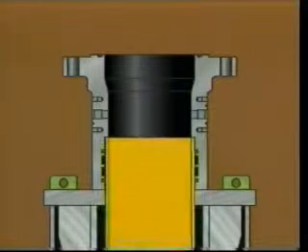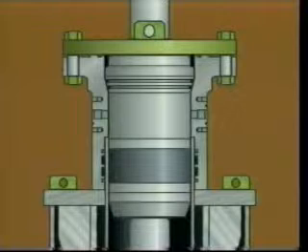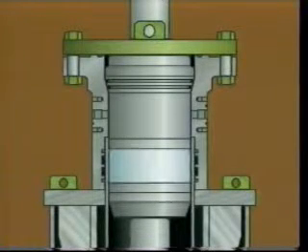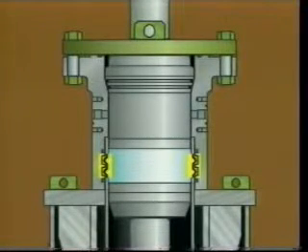Recently, a process was developed which hydraulically cold forges the casing to a specially machined casing head. For this process, patented by Cameron Iron Works, a combination forging and testing tool is installed. Hydraulic pressure is then applied in the forging tool, which exceeds the yield point of the casing, forcing the casing into grooves machined in the casing head. There are several advantages to this process. Time is reduced, no welding is required, and maximum integrity is maintained.